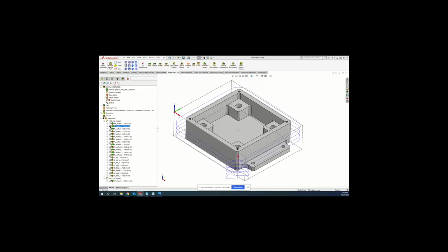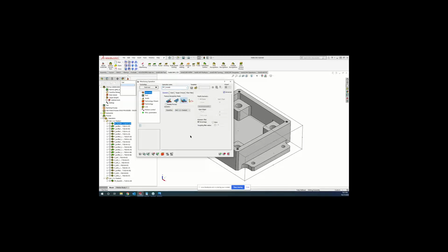I'm just going to show you real quick. In this particular operation, we're doing a profile to go around the outside, as well as a finish pass to finish that off down there. Now we can go ahead and open up our iMachining here, and we'll do the outside feature recognition. It is going to be looking at our stock, and it's automatically set to look at the stock. If we wanted to pick a different stock, we could browse to that one. If we're running a fixture, we'll have the fixture recognition available. You'll see that the fixture clearance is grayed out, currently 2 millimeters on this part, and I can't change that number. The only reason is because we don't have a fixture assigned to this part.